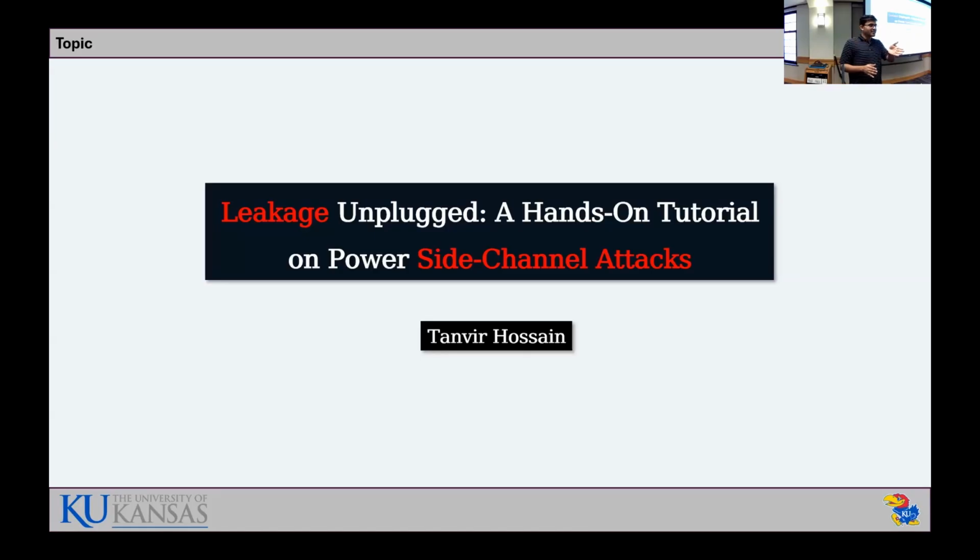So if someone is doing some malicious activity inside your processor, the power trace will be different. It will deviate. If your control flow is deviating from the secure program to a malicious program, that will be clearly visible in the power trace. In this way, you can protect your system.